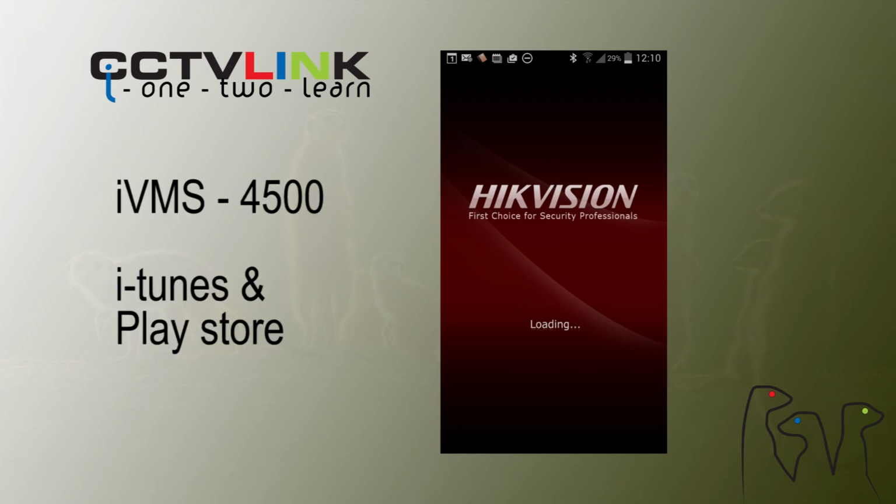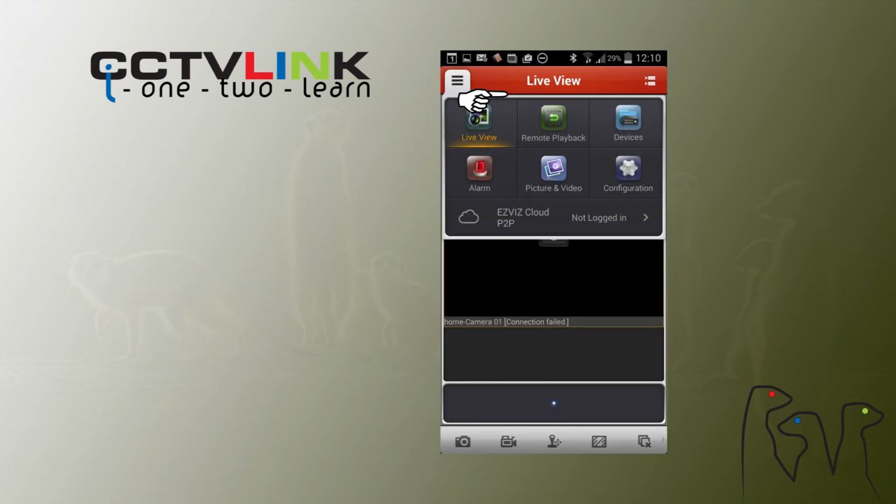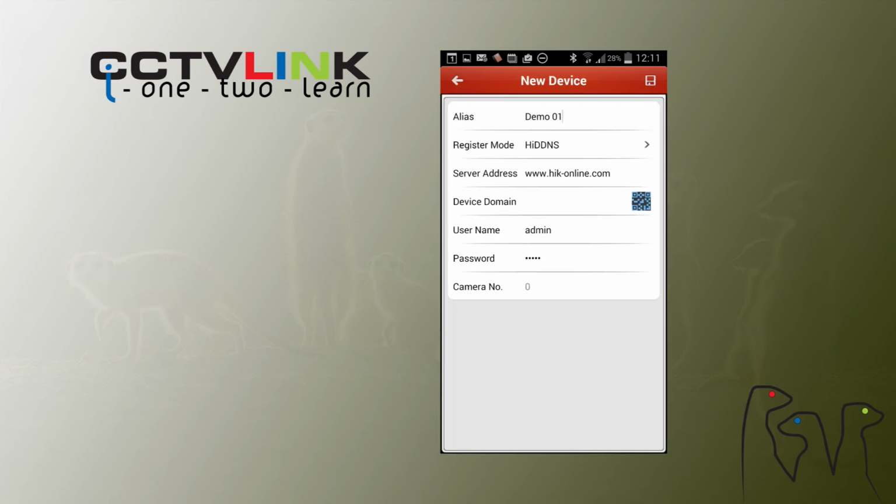For viewing on a smartphone, you can download the app, IVMS4500. Tap Menu Bar, tap Devices, then tap Plus, to add. Add a name for the DVR. In Register mode, choose HIDDNS. In Device Domain, enter the name you gave the DVR in DDNS setup. Use the admin and password of the DVR. Tap the Save button, and you should be connected.